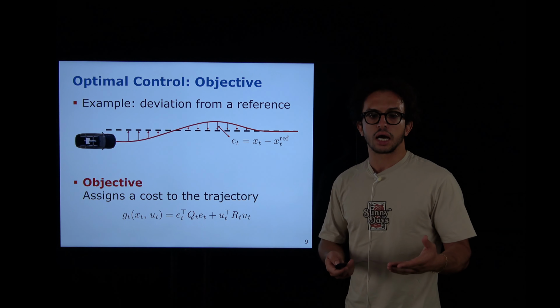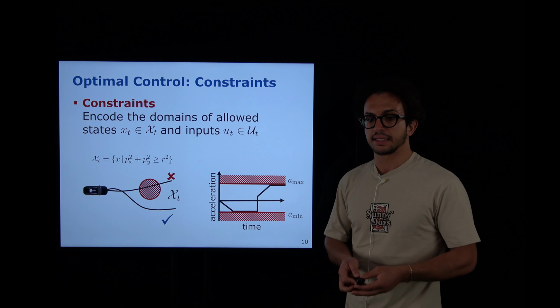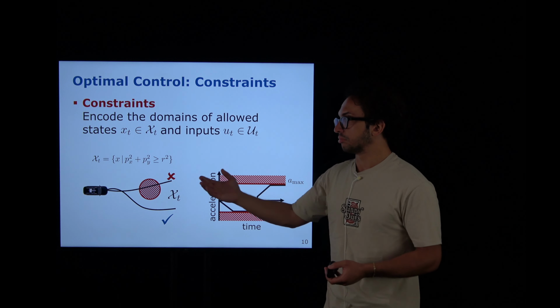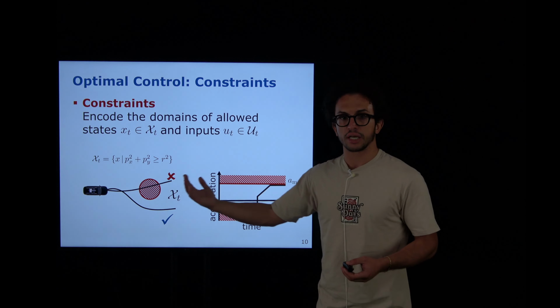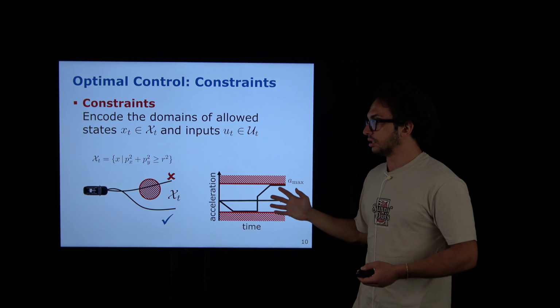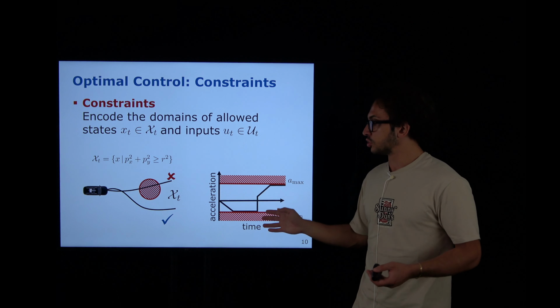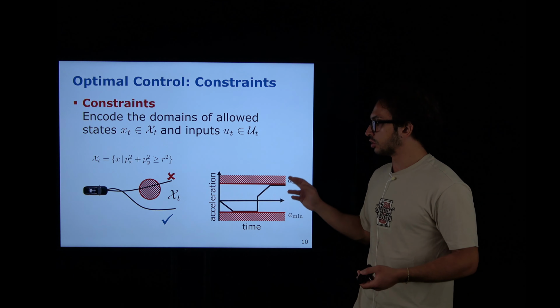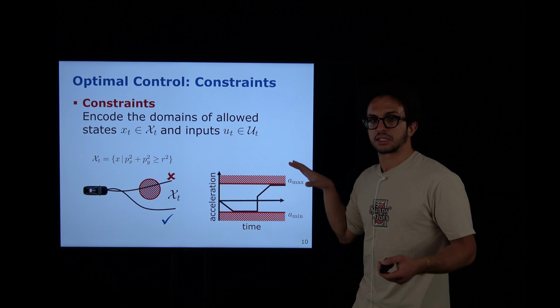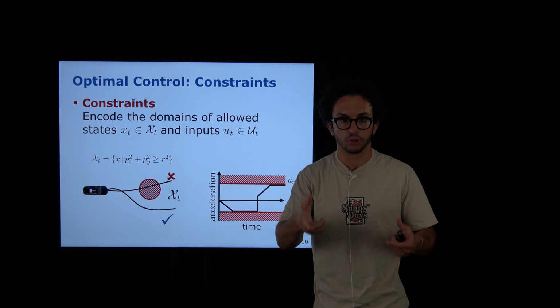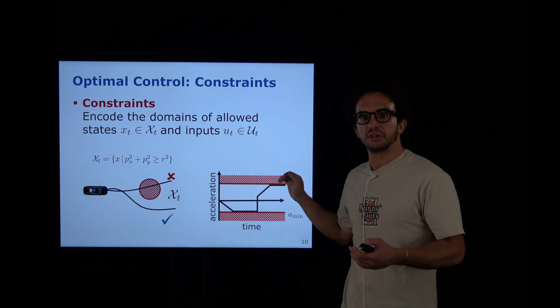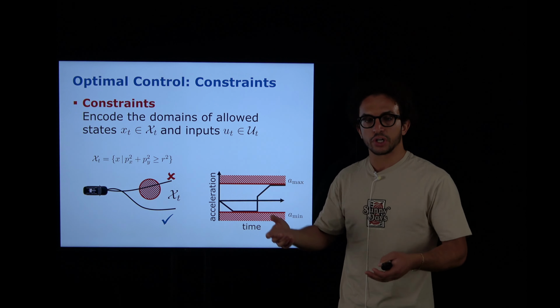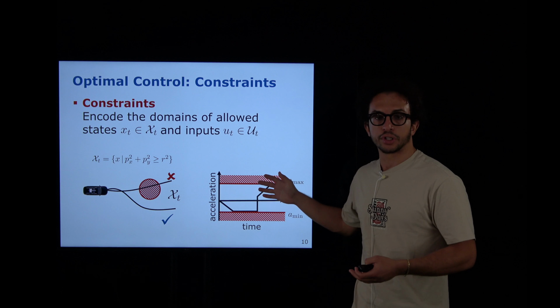And now we said we can also handle constraints. Well, as I said, the constraints can be the two main kinds of constraints. One, it can be the actuator effort. So we know that we cannot go above a certain acceleration. Like we wouldn't be feasible because the actuator we have, the motor we have, doesn't allow it.